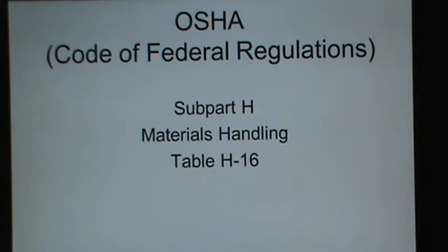We're going to go to a table now. Flip over a page or two and see if you can find table H16. I'm actually going to flip over more than a page or two, probably 4 or 5. We're talking about nylon rope slings here on table H16. And I want you to highlight this. Follow your left-hand column down to a 1-inch rope.